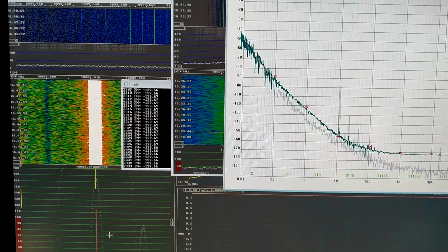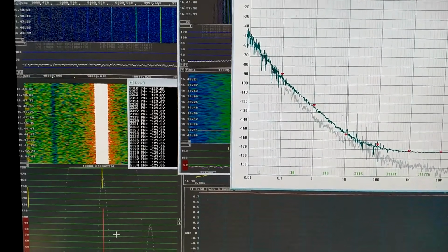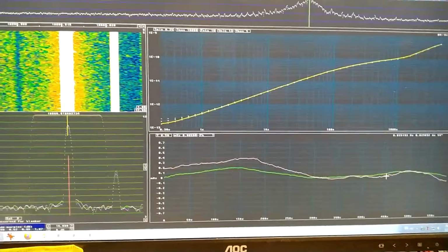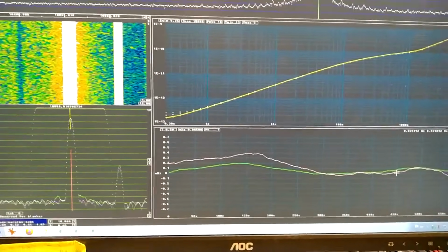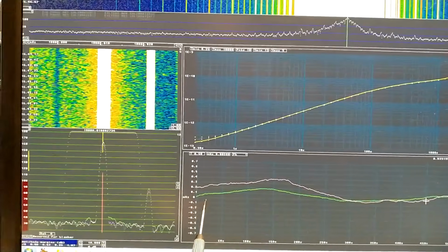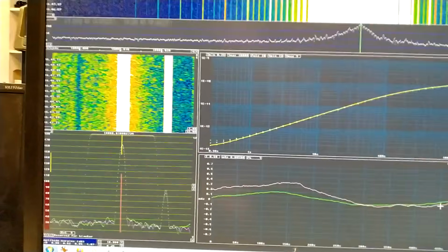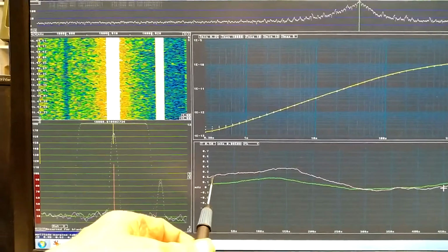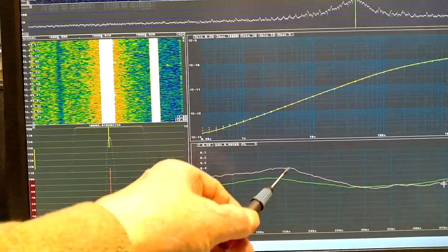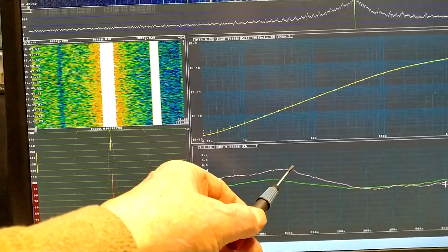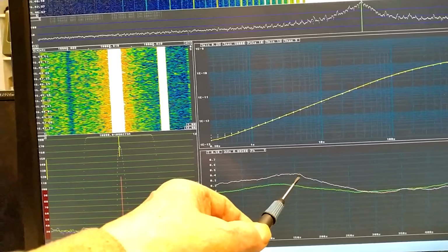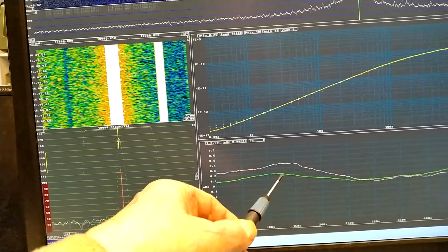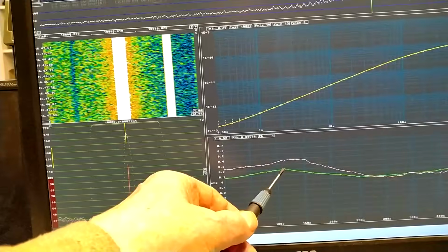It is the current for each crystal. The total current is 4 times larger because I have 4 crystals. Frequency versus time has a funny behavior. I think the green trace is the frequency change of my oscillator under test. The separation between the green and the red at this event means that the effect of changing temperature is slower on the channel 2 oscillator than on my unit under test.